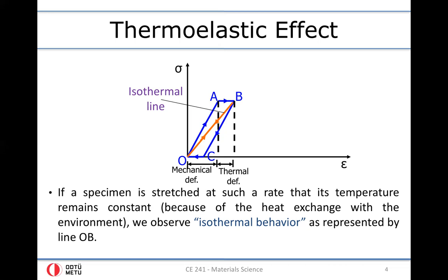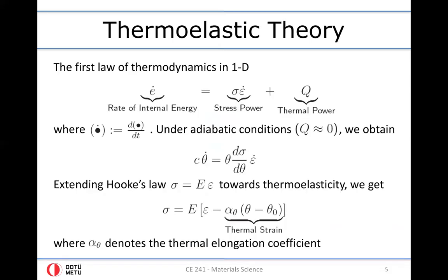What happens if you look at the phenomenon of thermoelastic heating or thermoelastic cooling in compression and tension, respectively, in the macroscopic thermoelastic theory? The equations you will see here will be relatively new, but you will grasp the concept if you think of things in terms of energy. As you know, the first law of thermodynamics says that energy of a system is preserved. In other words, the change of the total energy of a system in time is equal to the total energy that is supplied to the system.